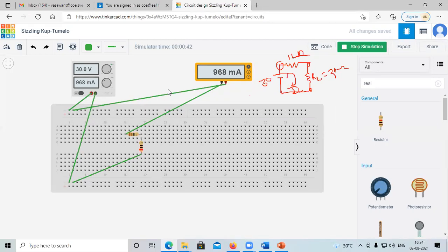Look, this PCB, you will know its connection. The power supply lines are horizontally short circuited, and these lines are vertically short circuited. So according to this, if we do the connection, I have taken one busbar as positive to avoid complication and another busbar as negative, connected the circuit and started the simulation. So hence we verify the result.